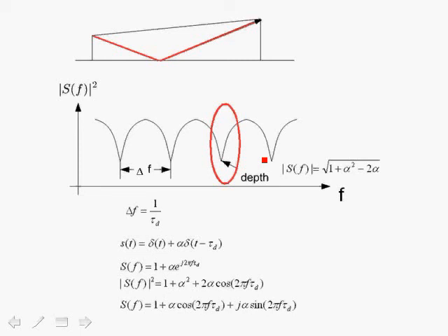an office environment. So to summarize, multipath does create a big problem. Depending on the delay, you have fading situations which bunch up together if the delay is large, and you have fewer of them if the delay is smaller within a bandwidth. And the depth of the fade is dependent on the magnitude of the reflection. The larger the reflection, let's say off a barn or something that reflects the ray with a lot of power, then of course the fade will be deeper, and the more the attenuation and the more the problem.